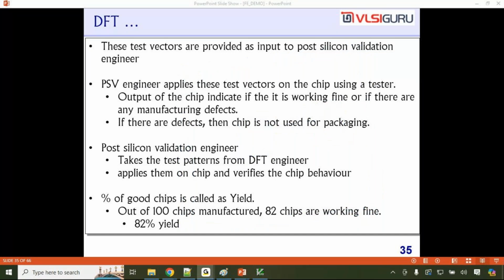Chip is very small, right? Let's say I give you this kind of small chip, which is 1 centimeter by 1 centimeter, very small one. Just by looking at the chip, can you tell this is good or this is corrupted? You cannot tell, right? You need some kind of techniques. That technique is the DFT technique. What they also do in parallel is change the circuitry itself a little bit. They insert something called BIST logic, built-in self-test logic. Meaning my mobile phone chip itself will have some testing logic inside it.